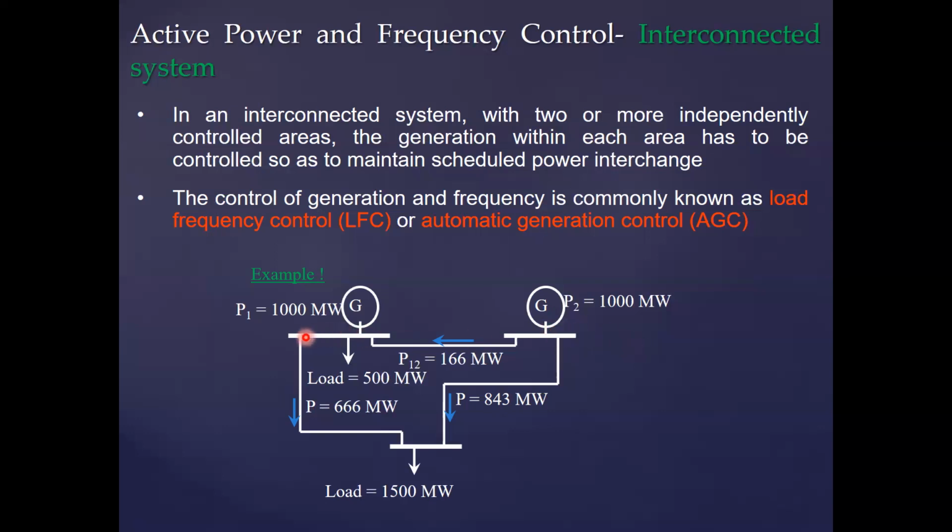We solve these algorithms, which we call load flow algorithms, in such a way that the voltage is obtained. These are the generator buses here, and these are the load buses here. When we do the load flow analysis, we consider one of the buses as a slack bus, the reference bus, and with respect to the slack bus we estimate the bus voltages, here or over here.